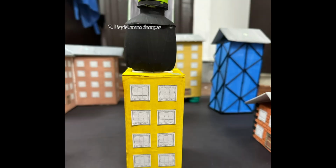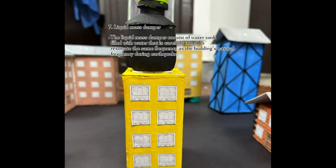7. Liquid mass damper. The liquid mass damper consists of a water tank filled with water that is carefully tuned to resonate at the same frequency as the building's natural frequency during earthquake. When the building sways in one direction, the water sloshes in the opposite direction, which dampens the building's movement and minimizes the sway.